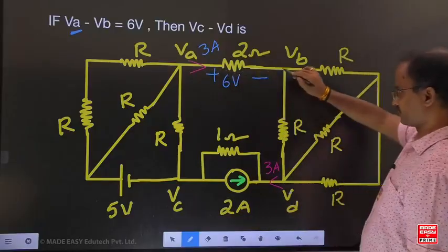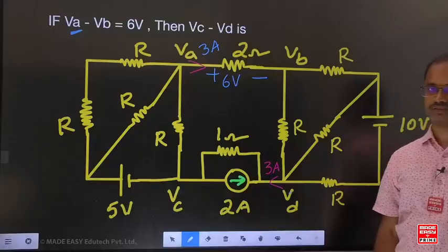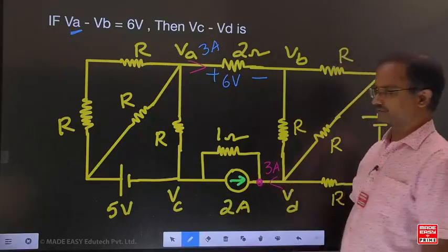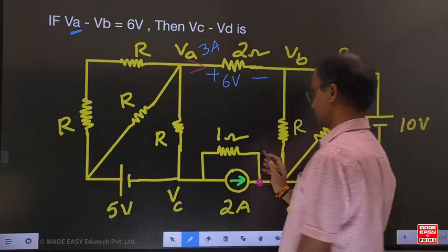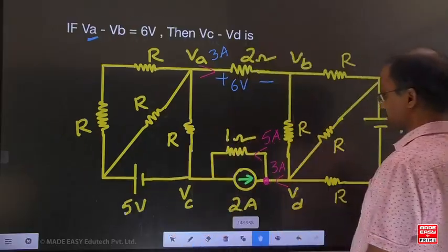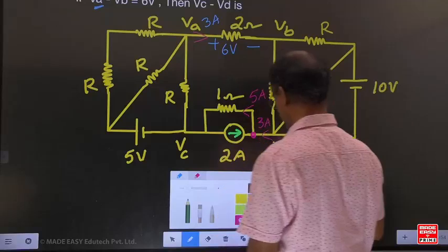For this example, 3 amperes is coming here and it distributes in all the branches. Finally, how much current comes outside here? 3 amperes. If you apply KCL here, how do you write it? 2 is incoming, 3 is incoming. But this current, how much? 5 amperes.